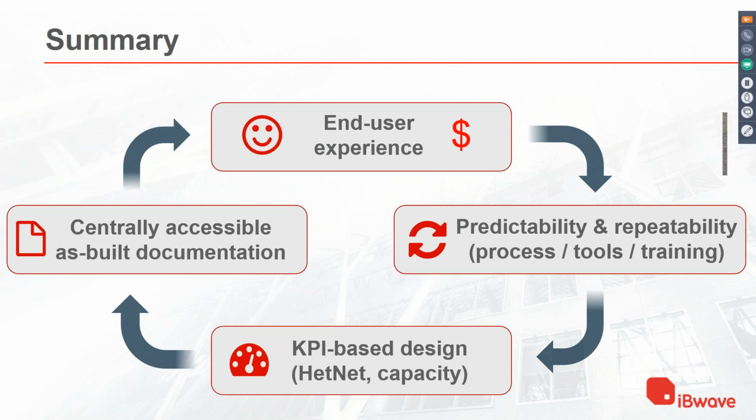So I think right there that's being addressed. But importantly, as I mentioned before, you want to be able to account for interference, so it's important to do an RF walk at the beginning and make sure that's taken into account in the design. And so that's how this is addressed.